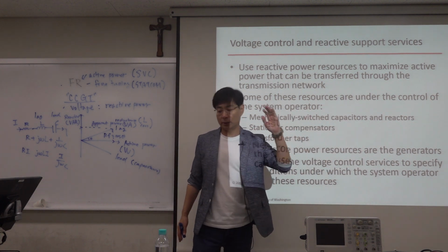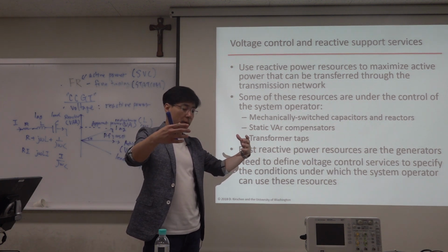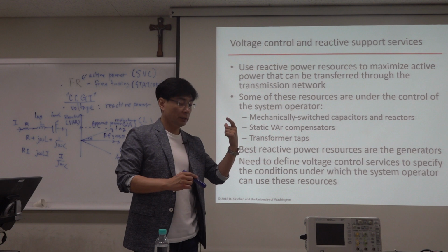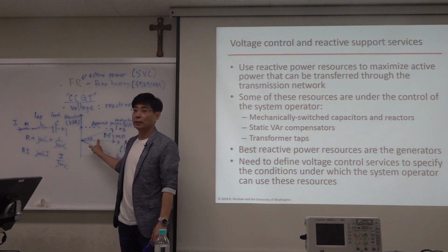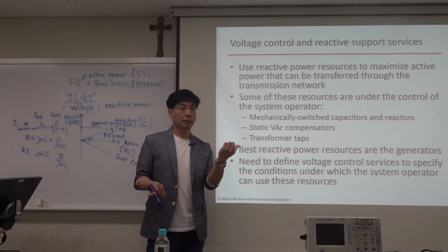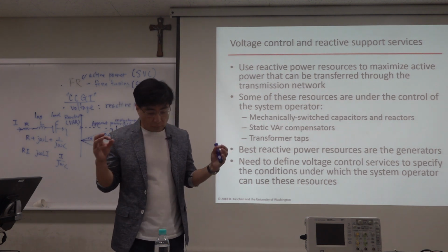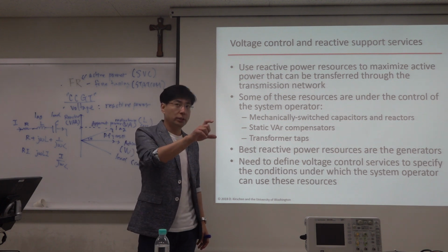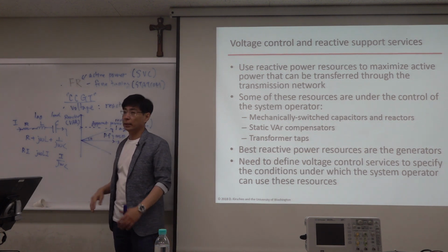And also the PV solar generation. We have a power electronics device. So the PV inverter changes from DC power to AC power, but while doing that, it also can adjust this theta. So solar panel, the inverter, also can provide reactive power and can control that. Okay, so obviously, if it wants to deliver the maximum amount of active power, this theta should be 0. But sometimes to change the voltage, it needs to support reactive power somehow. So it can change this theta angle.